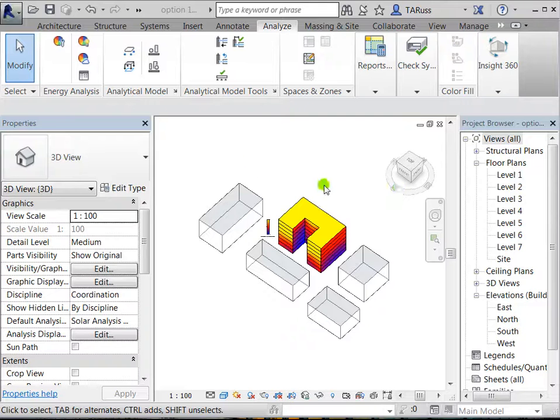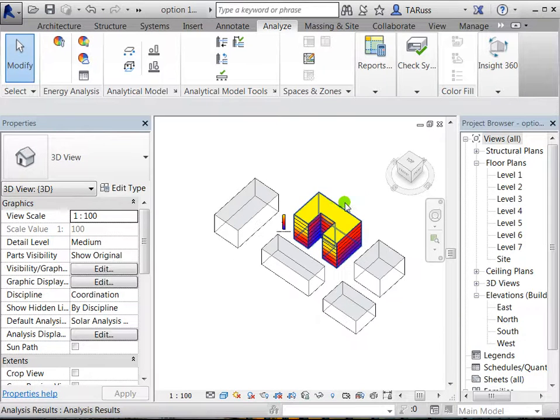So let's get this out of Revit and into Flow Design. Flow Design doesn't give you the option of choosing where the wind comes from. It just gives you one vector, and then you can rotate your file around so that you can actually show what the prevailing wind pattern would be. That's kind of the point of this. In Calgary, the prevailing wind tends to be out of the west, northwest, so I'm just going to remember that when I bring it into Flow Design.